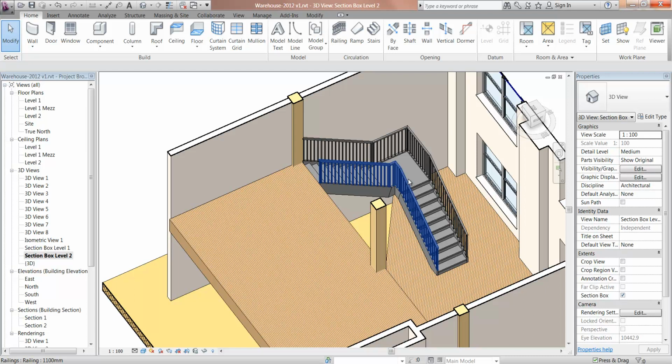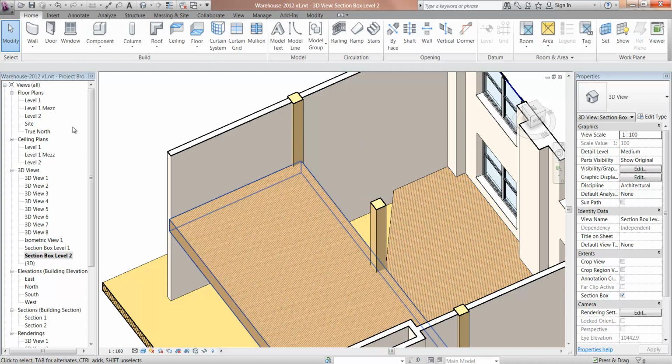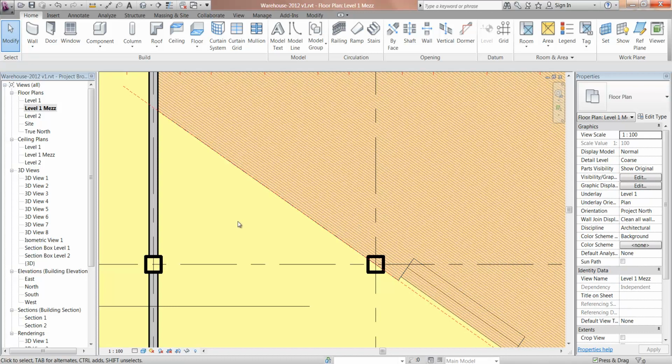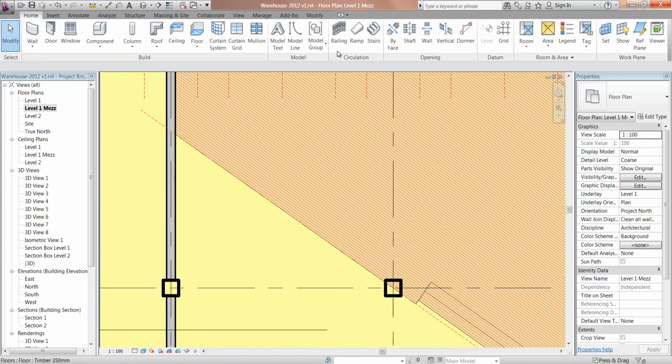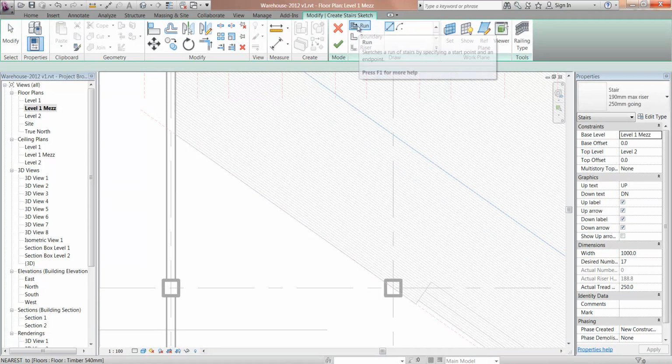Okay, so you can work in sketch mode, hopefully, if you are comfortable drawing things like floors and other things that are created in sketch mode. It should be pretty straightforward. I'll just go and show you now, again using the Stairs tool, how to do basically something very similar, but not with the run tool. So using the boundary tool and the riser tool, I'll start by drawing some risers.